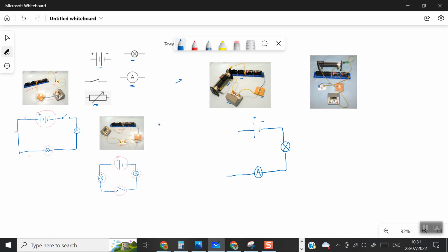And then it is connected to a light dependent, or a variable resistor, which is this one here. A variable resistor is just one that you can change the resistance on. So again, we just draw the symbol for a variable resistor. It looks something like that with an arrow going through it. And then that is connected up here. Okay, so that's that simple circuit.